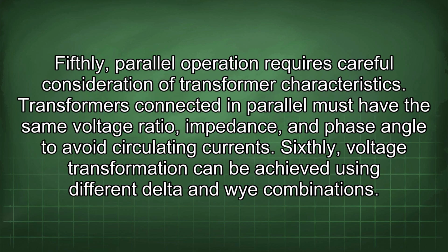Fifthly, parallel operation requires careful consideration of transformer characteristics. Transformers connected in parallel must have the same voltage ratio, impedance, and phase angle to avoid circulating currents.